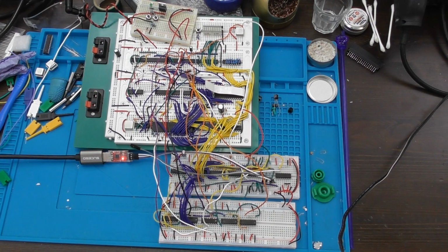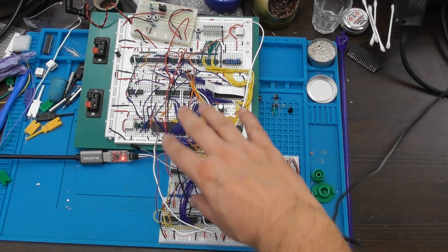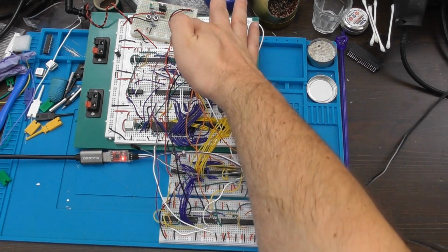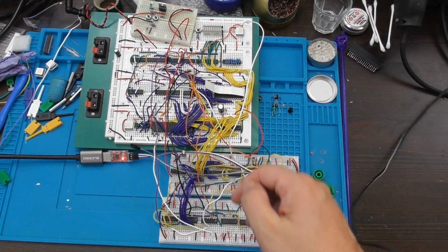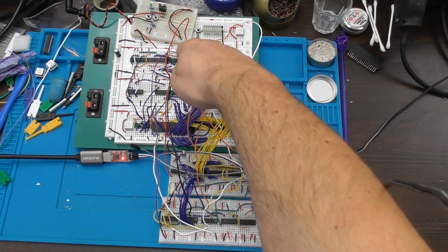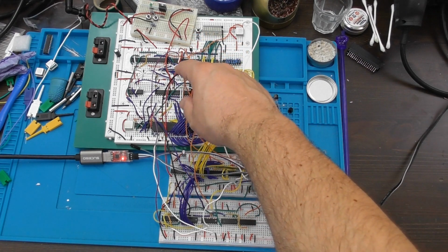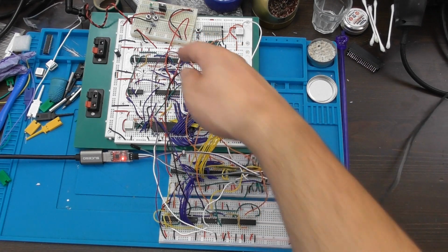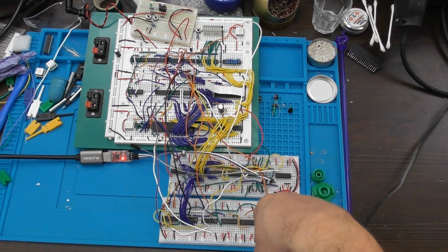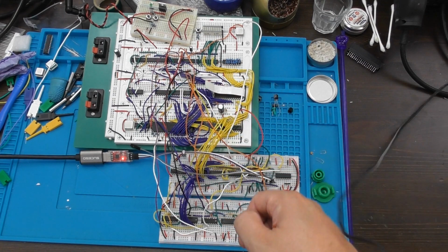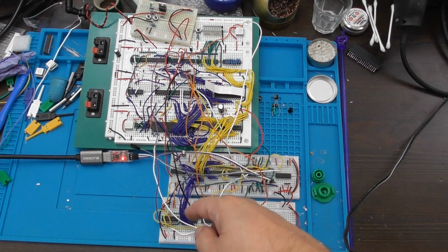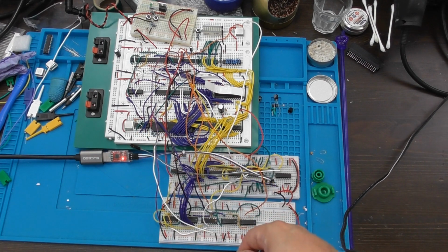Right, here's the new circuit all wired through to the rest of the circuit here. The main wires here are going to the decoding logic up here. I've also got some rather long orange and black wires here which are going to a spare inverter on the main circuit board, and that's for the additional inverters that I pointed out in the schematic that I forgot about the first time round. So that's actually not down here at the moment, that's all sharing one of the ones up there. The IRQ is connected through to the CPU.